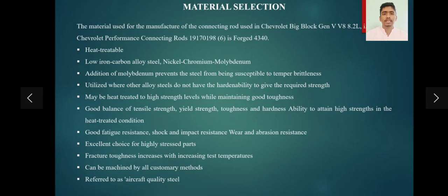Good balance of tensile strength, yield strength, toughness and hardness, with the ability to attain high strength in the heat treatment condition. Good fatigue resistance, shock and impact resistance, wear and abrasive resistance. Excellent choice for highly stressed parts. Fracture toughness increases with increased test temperature. Can be machined by all customary methods. Referred to as aircraft quality steel.